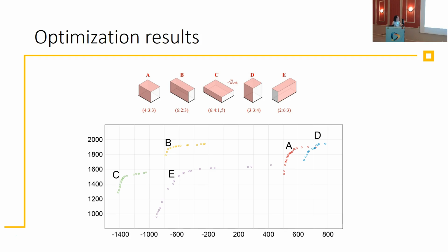And to repeat, the vertical surfaces use either overhangs on the south facade, an overhang for each floor, and the east and west facades use vertical louvers, which is found to be most optimal for these directions.